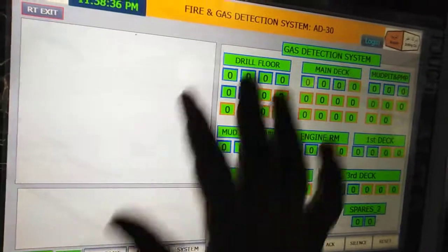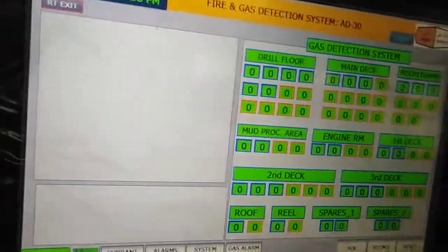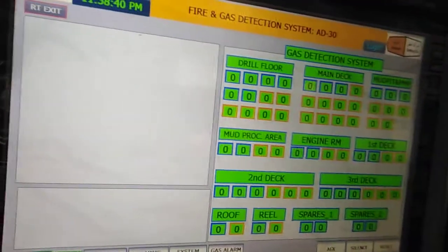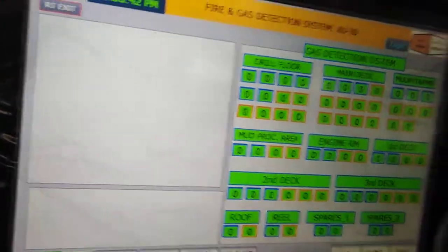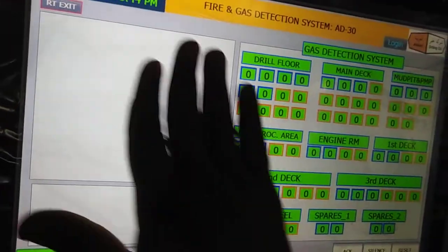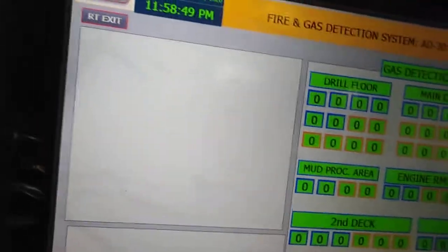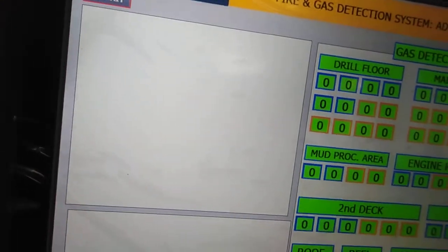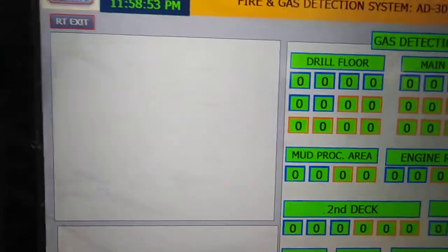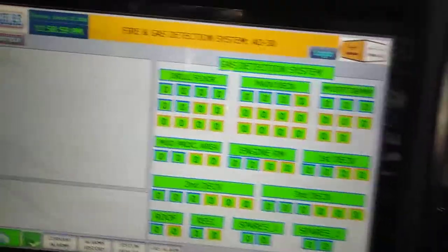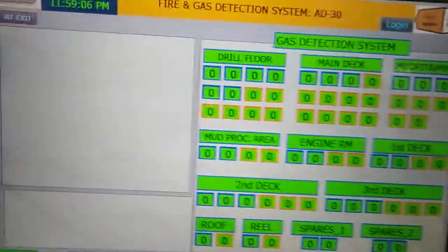This portion is dedicated for the fire system. Also we'll incorporate some more features in this one. Also the fire system is a Modbus based system with Tyco Minerva T2000 panel. So for that system also we are planning to prepare a fully dynamic type HMI where anybody can change all the details, and anybody can make any configuration.